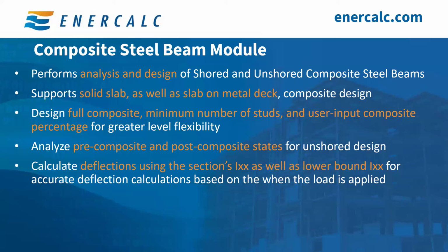The first thing that it can do is, of course, analyze and design shored and unshored composite steel beams. It supports solid slabs as well as slab on metal deck composite beam design, and it does full composites. It also allows you to pick the option to say, hey, I just want the minimum number of studs, or a user input composite percentage for a greater level of flexibility.